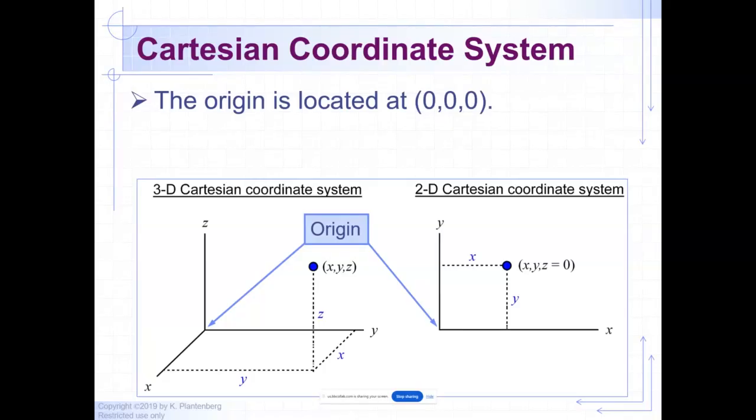So if I go over to the right and up, it's always positive. Those are always positive coordinates. If I'm typing in a relative coordinate or if I'm typing in an absolute coordinate, I'm going to go over. Positive is right and up. Negative is left and down. So you have to remember that. Very important.